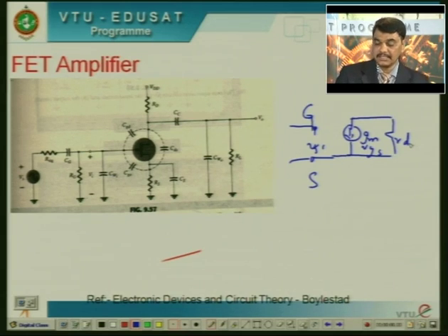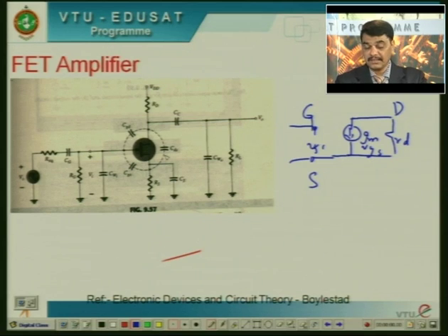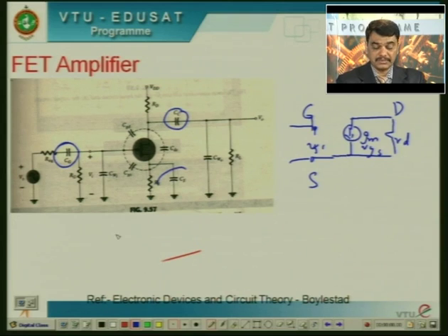At high frequencies, there are external capacitances, CGD, CGS and CDS, and the reactance of the capacitors CC, CG and CS approaches 0. Therefore, this RS and CS combination acts as a short circuit, and similarly CG and CC behave like short circuit elements.